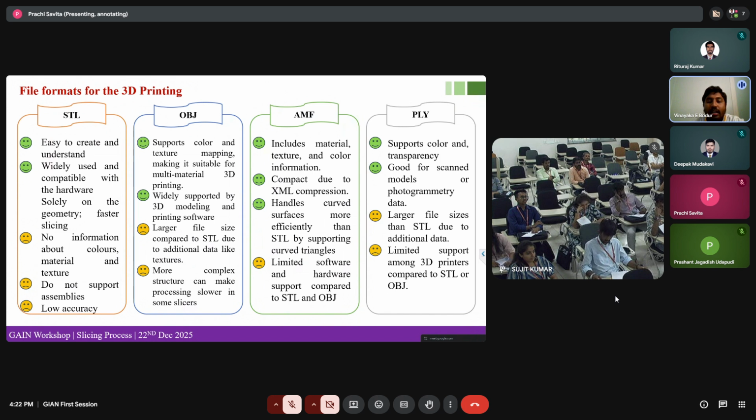It lies in the types of polygon supported. While STL is strictly limited to triangles, OBJ files can store quadrilaterals, hexagons, and other complex polygons, as well as freeform curves and surfaces. This geometric flexibility allows for a more efficient representation of certain shapes, often providing higher accuracy with fewer elements.